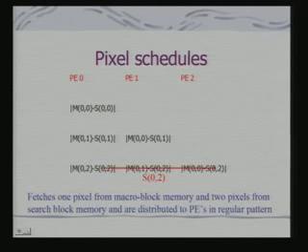Here you will find how S02 is taking care of this same data. This is your same S02, and I can use the same data over multiple macro block pixels, and these macro block pixels are traversing along the diagonal path over the PEs. So, that traversing and fetching regularity pattern gives you the efficiency in computation.